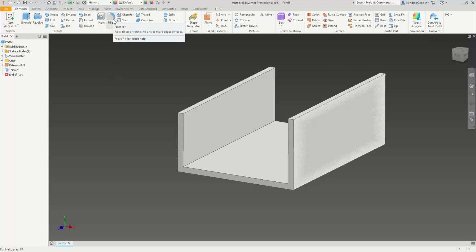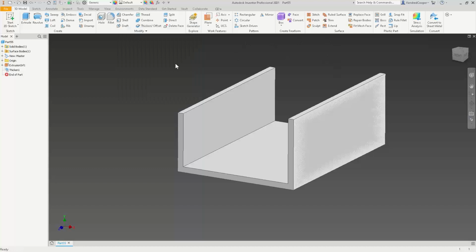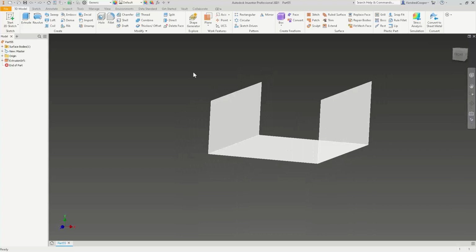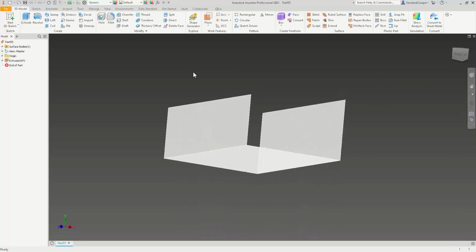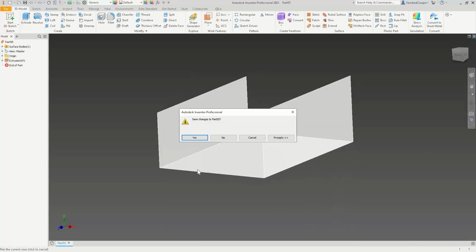There are times where you can't get a fillet to apply on a solid model edge because of some of the blends that's taking place into other geometry. Whereas with surfaces, that's only going to be a factor if all of those surfaces are stitched together. That's one of the things to look at when you're creating surfaces is, are they seen as one contiguous blanket or joined or stitched together quilt, or are they some other broken up piece of geometry, separated surfaces, for example.